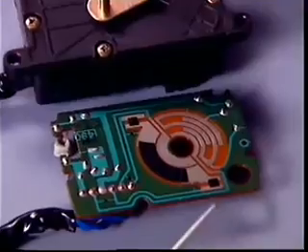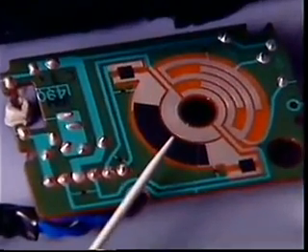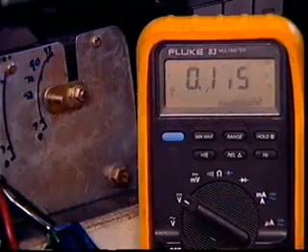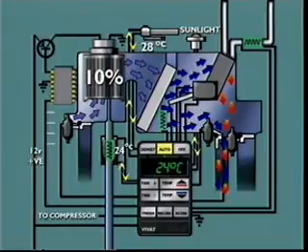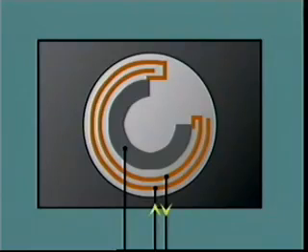Some electrical servos also utilize a carbon film potentiometer to signal to the electronic control unit the position of the blend door and, if it is moving, the direction in which it is traveling. A voltage from the electronic control unit is applied across the potentiometer. The wiper is connected by the signal wire to the electronic control unit.